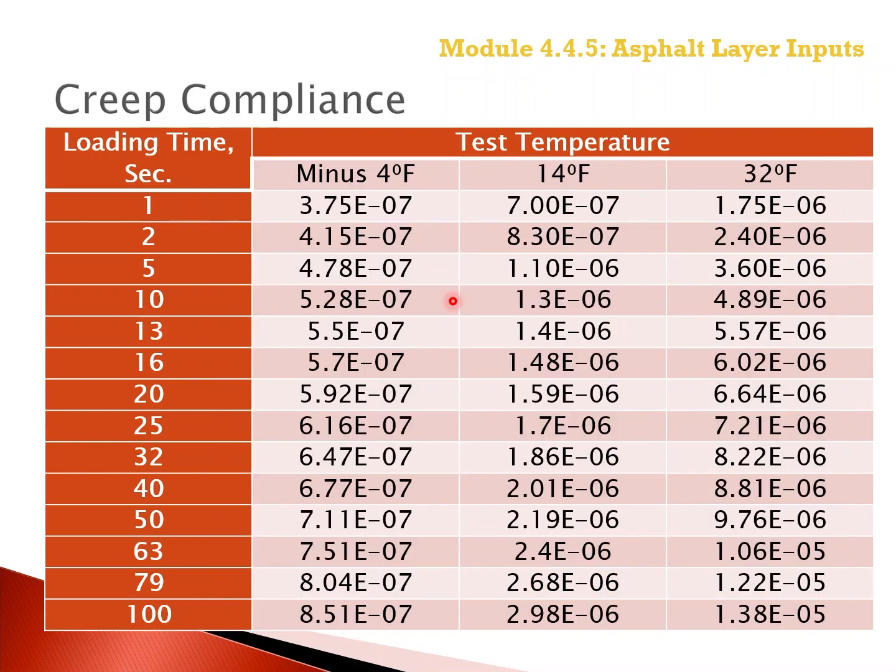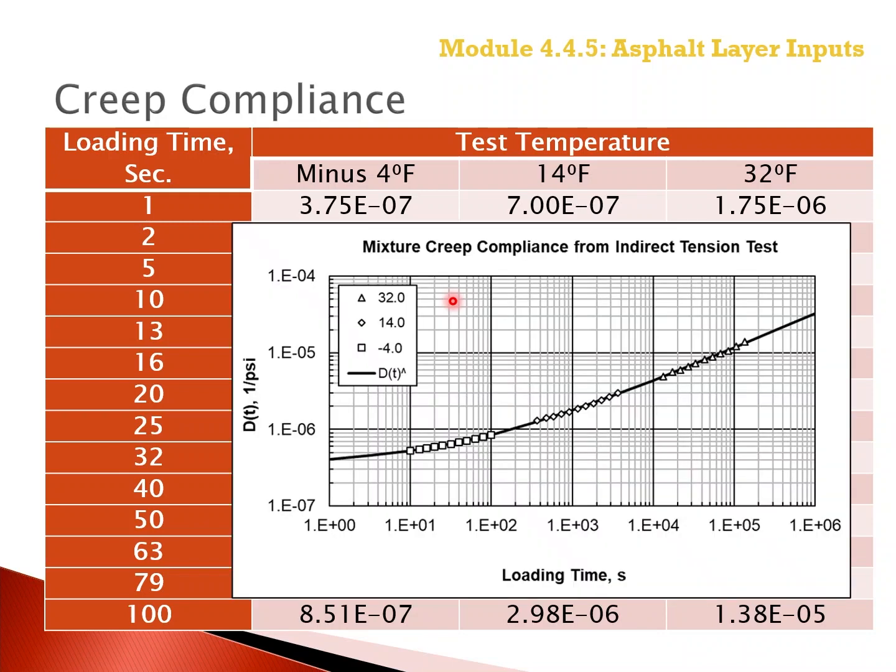The table shown on this slide is another example of the creep compliance values measured at different test temperatures and loading times as defined in AASHTO T322. The creep compliance master curve created by the PMED software is illustrated in the chart also shown on the slide.